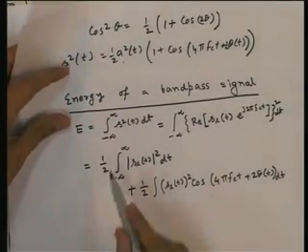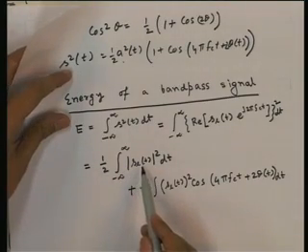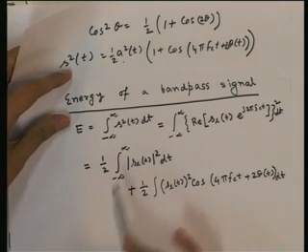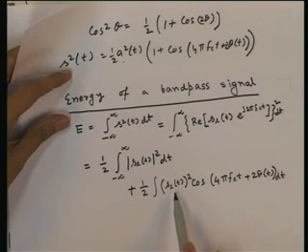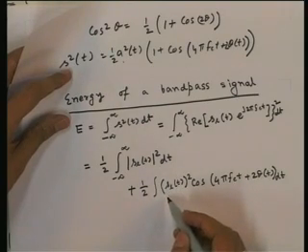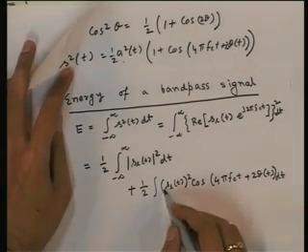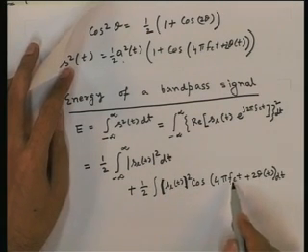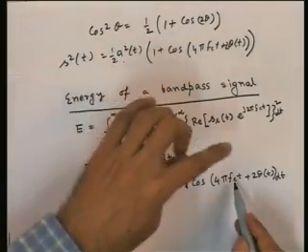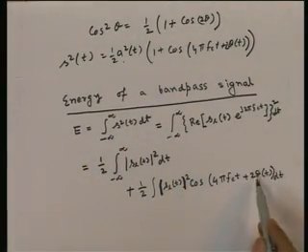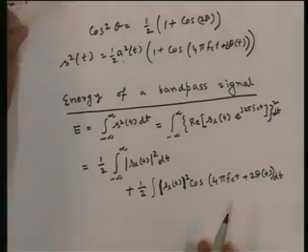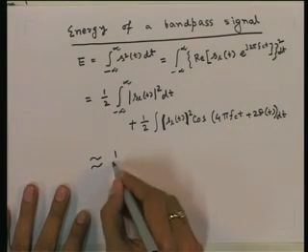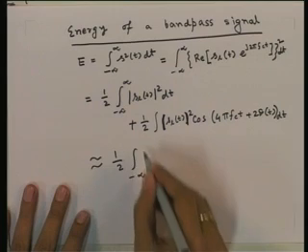If you integrate half a square t, it is nothing but half of the magnitude of s_l(t) squared, because a(t) is the magnitude of s_l(t). So, we have this part and then half the integral of the magnitude square of s_l(t), times cos of 4 pi fc t plus 2 theta t, dt. Once we have this, it can be written approximately as only the first part.